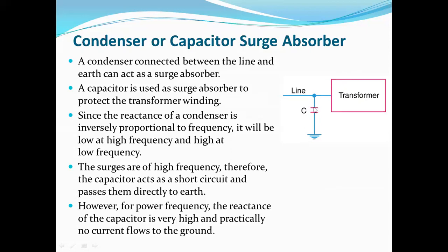What is the relationship between the capacitive reactance and the frequency? Xc is equal to 1 divided by 2 pi fc, so our capacitive reactance is inversely proportional to the frequency. If we increase frequency, then the capacitive reactance gets decreased, right?